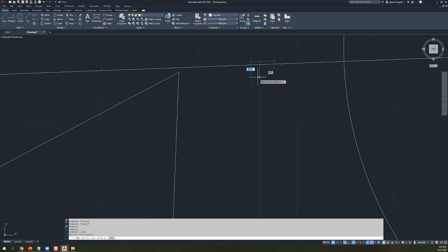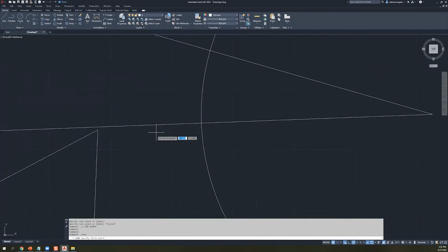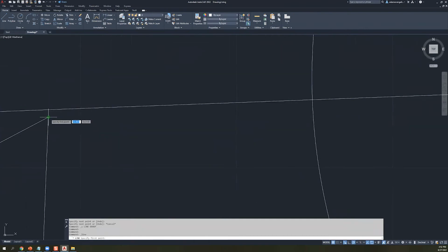And so, if I wanted to do something like this, or actually I know what I want to do. If I wanted to do something like this, I'm going to mouse over here. That's a point of interest. This is another point of interest. What if I were to just start this out here, do the horizontal, and then I want to do straight down over here. I'm going to pull off that reference point and then snap it over here as well. And now that's a perfect horizontal 90-degree bend.